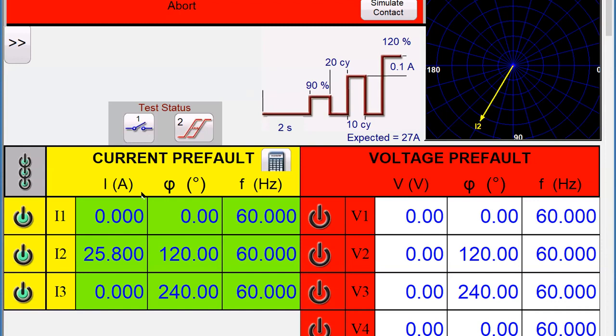And again, you're seeing here, see how the increment in the pulse? As I look at 3, this will be my C phase. You'll notice that this is actually pulsing. It looks like it's ramping, incrementing up the value, but actually what it's doing is pulsing it on for a 10 cycle delay on and 20 cycles off. So each one is actually working.